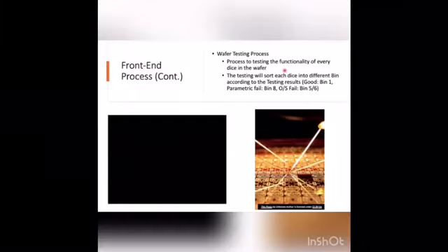For front end process, there is a wafer testing process, which is the process of testing the functionality of every die in the wafer. The testing will sort each die into different bins according to the testing results.